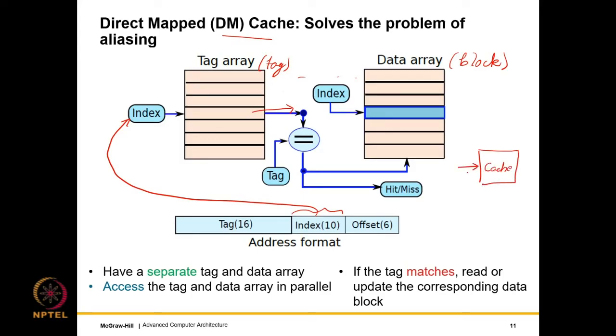If it's a load, if it's a read, we give it the address and out comes the data if the data is there, otherwise we get a miss signal. Along with that we get a hit/miss signal. So the miss tells us that the data is actually not there.